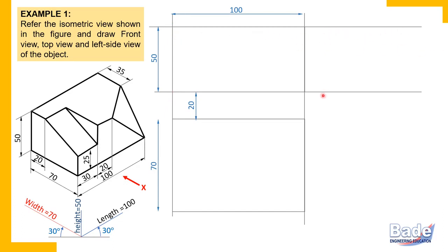These two horizontal lines are called end projectors, because they come from the top end and bottom end of the front view. So the end projectors from the front view to the side view are horizontal.